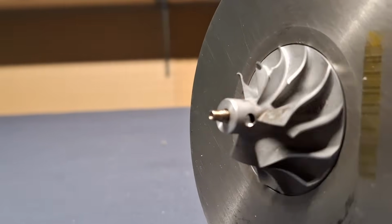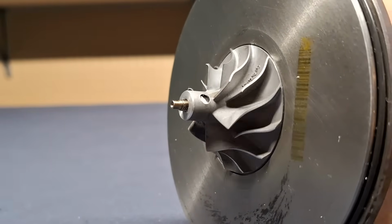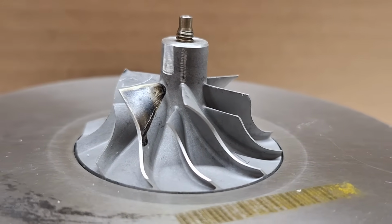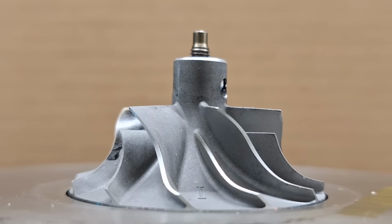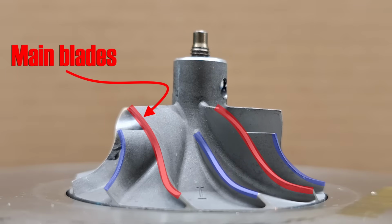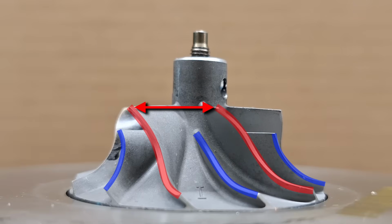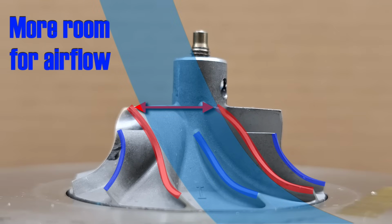In addition to inducer and exducer diameters, compressor wheel blade design and number of blades play a major role in turbocharger performance. This compressor wheel is a typical modern design that employs splitter blades. A design like this leaves more room between the main blades, which allows a bigger bite of air, which allows improved efficiency and better airflow, especially at high RPM, because it leaves more space for the air to pass through.